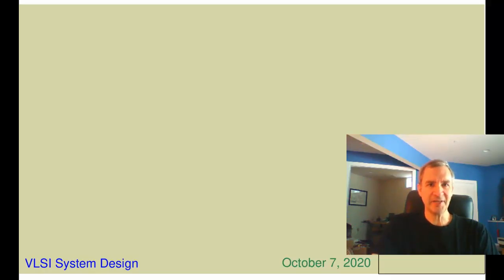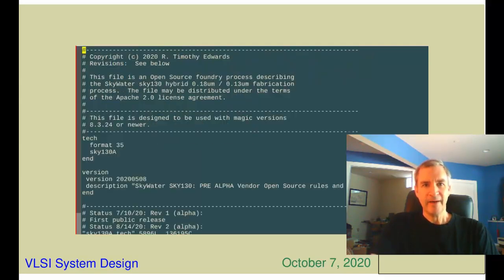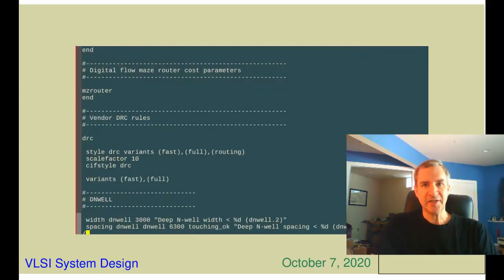Are you ready for a challenging example? A challenging DRC problem is one that can't be described by any of the simple DRC rule types in the DRC section of the Magic Tech file. Instead, you'll have to figure out how to describe the area as a geometrical construct, very similar to the way that Calibre describes error checks in a Calibre rule deck. You'll want to use the CIF output section Boolean operators like OR, AND, grow, shrink, and so forth to work in a way that after all the operators are applied in sequence, whatever is left over is by definition an error. There's a way to tie this into the DRC section of the tech file.